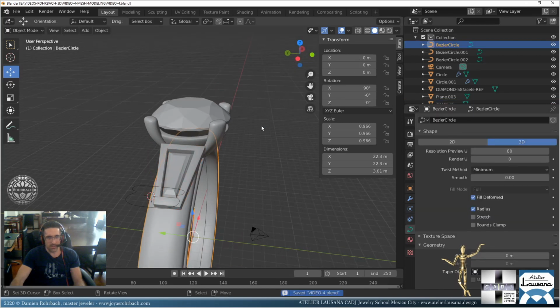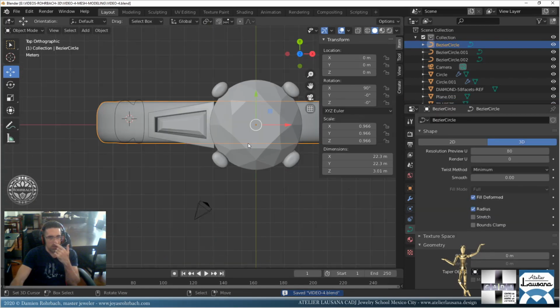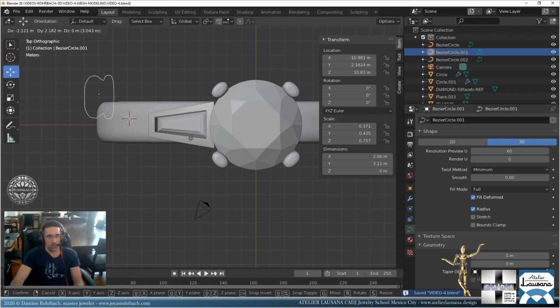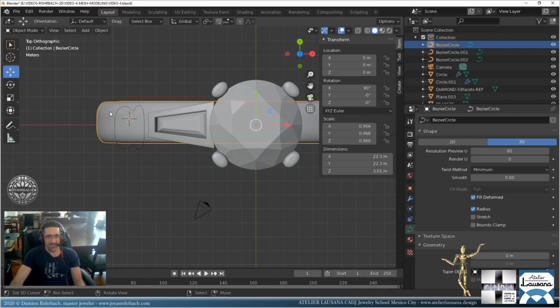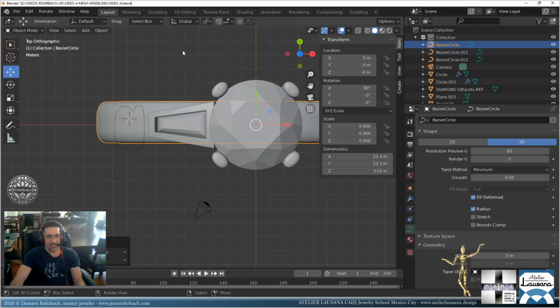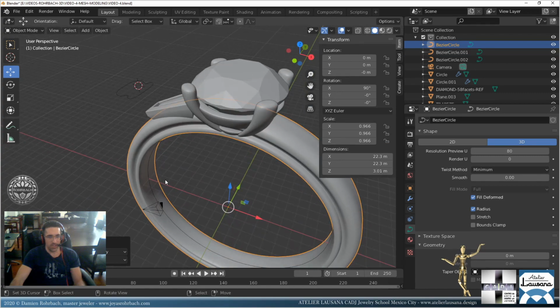Okay, the ring is not centered. Somebody is not centered right here. Who is not centered and why? Okay, maybe my profile. No, but the position of the profile has nothing to do with it. You can move the profile wherever you want. That will never affect the beveling geometry, okay?